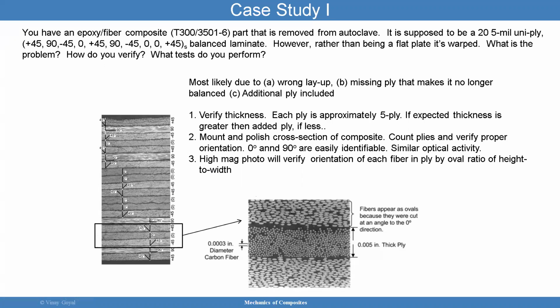Now, looking at the fiber systems, I've talked about how many different fiber systems you can have. What you see here is a T300. T300 is a fiber produced by Toray, which is a company called Toray Composite Materials America, Inc. Typically, this kind of fiber system tends to be very high modulus fibers. And the baseline is a very nice carbon fiber. It's a baseline carbon fiber used in aerospace applications and has a lot of history, over 20 years, and even over 30 years of production history.